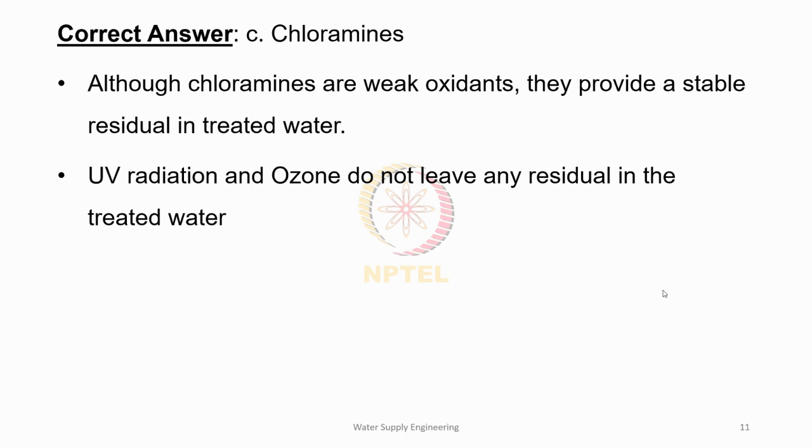The other options, that is UV radiation and ozone, both do not leave any residual, and as we know, boiling definitely doesn't have any residual characteristic. During the time of boiling only, the microorganisms will be killed.